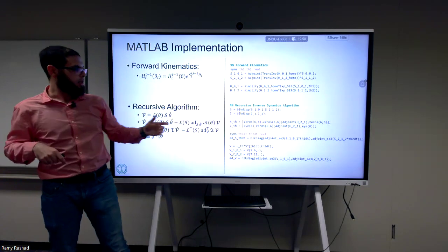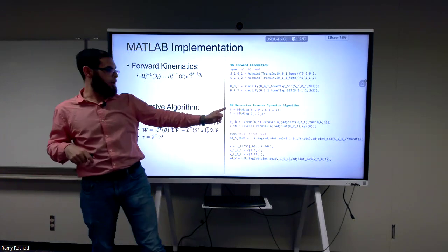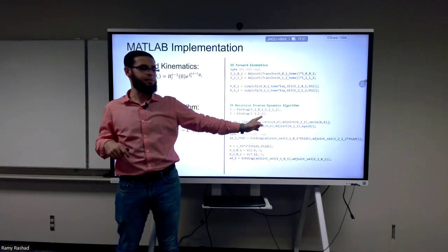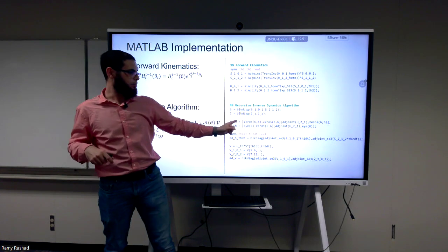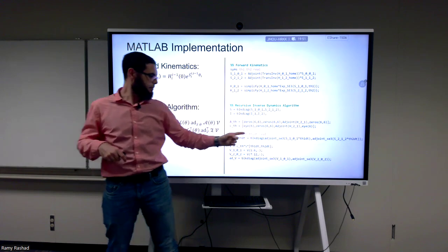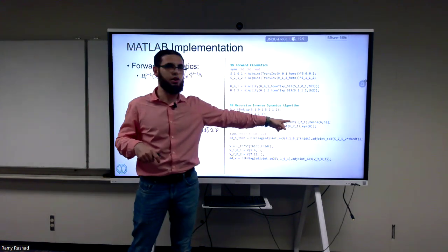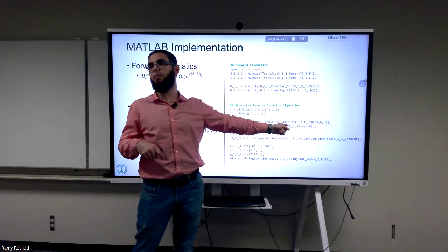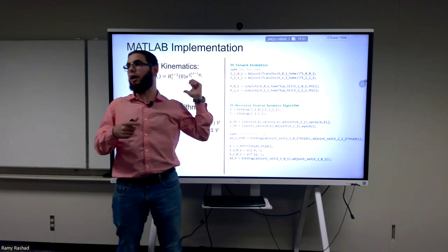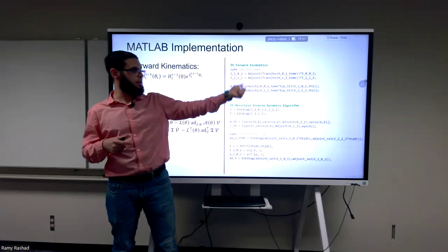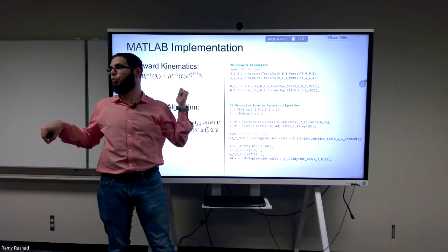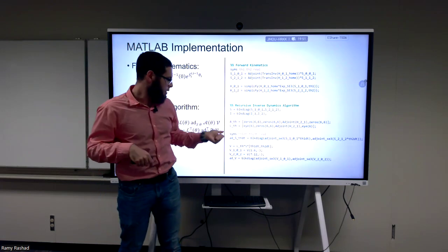It simplifies the expressions. The S here, you define it by the block diagonal of all of these terms. The I is the block diagonal of these two expressions. The A theta is given by that term. The L theta is given by this term. And you see everything here is nothing other than just that joint. That joint here is also implemented. So you can implement it for yourself. It's very easy. Or you can find that a lot of people already implemented it. In this implementation, I'm using the MATLAB implementation of the book, the Modern Robotics book.